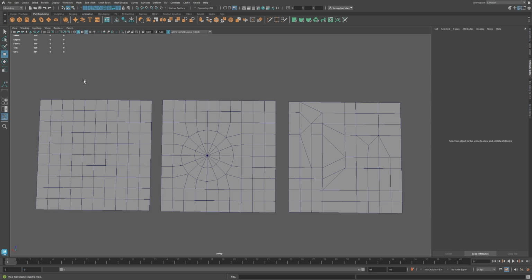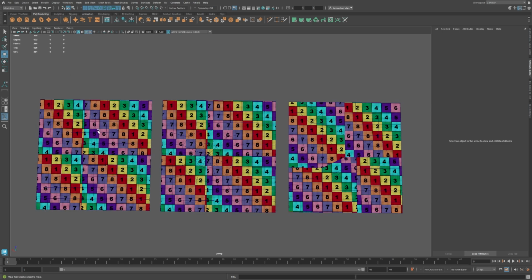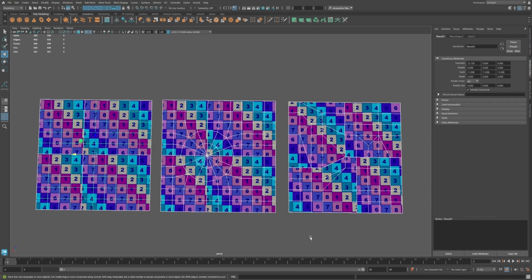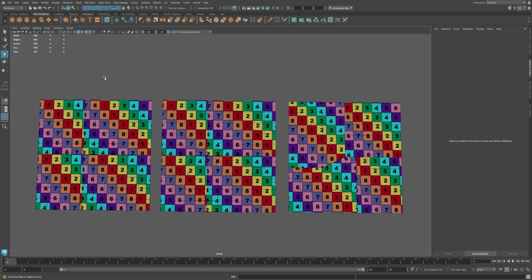Okay, now let's look at this example. But instead of these being laid out on one UV grid, they've been cut. So here we can see the UV cuts where the edges are bolded. This is an option that's used all the time to increase the resolution of the UV tiling on those surfaces. Now here, if I set these to smooth, we can see the effects. We have a lot of stretching and pull throughout here because we don't have an even support around where these UVs are cut.